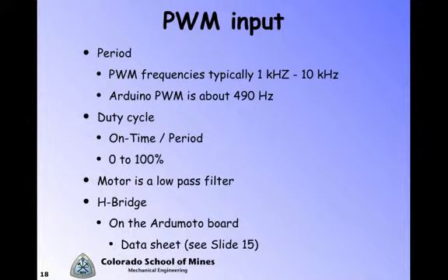And so we get this on-off behavior being transmitted through the H-bridge and therefore providing the power to the motors. And you may want to go back and look at the data sheet on slide 15 to see how that H-bridge is provided with the inputs from the Arduino.